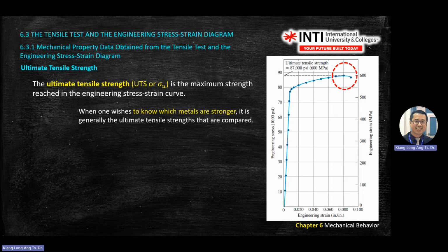For those people who are not good in material engineering, they might think that, oh, your product is better than another company's. Even with different brochures, one gives you the yield value, one gives you the UTS value. By comparison you think, oh, this one is higher so it is good, but actually you are reading the wrong things. It depends on application. Because on brochure, on catalog, they want to sell you something. Of course, they will use a better value. So when you read carefully, they will give you the UTS value, they will give you the yield value.